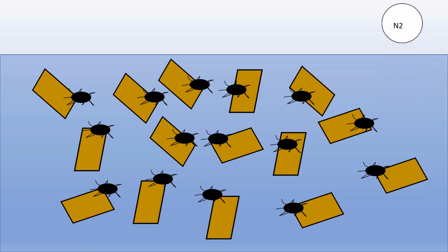Oh, by the way, 78% of the atmosphere is dinitrogen gas, so that's not really a problem. If the treatment doesn't go on long enough, you'll get some kind of intermediate gases, some greenhouse gases, nitrous oxide, etc. We don't want that. So really it's about letting it treat for a certain amount of time. But as you can see, these bacteria are powerhouses for transforming these chemicals, these contaminants, and putting them into a more desirable form. Just as importantly, getting them out of the water.